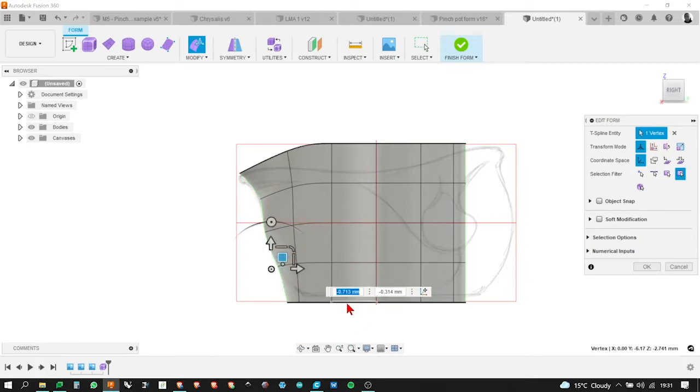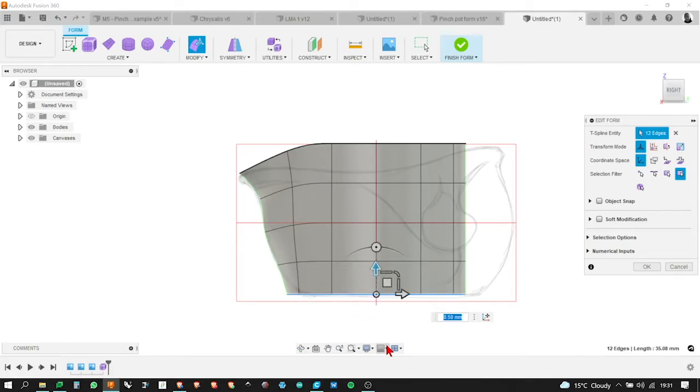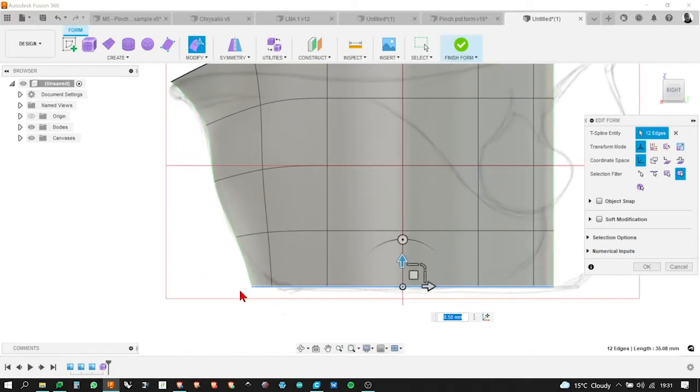The bottom here, I'm going to double click on the whole line and just bring it up slightly because that's where my sketch kind of is. Nothing's trying to be too accurate here. I do want to keep the bottom of my jug flat for obvious reasons. It will sit on the table much better if it's flat. So in my mind, I'm always thinking I don't want to do anything which is going to impact on that bottom surface and make it wobbly.